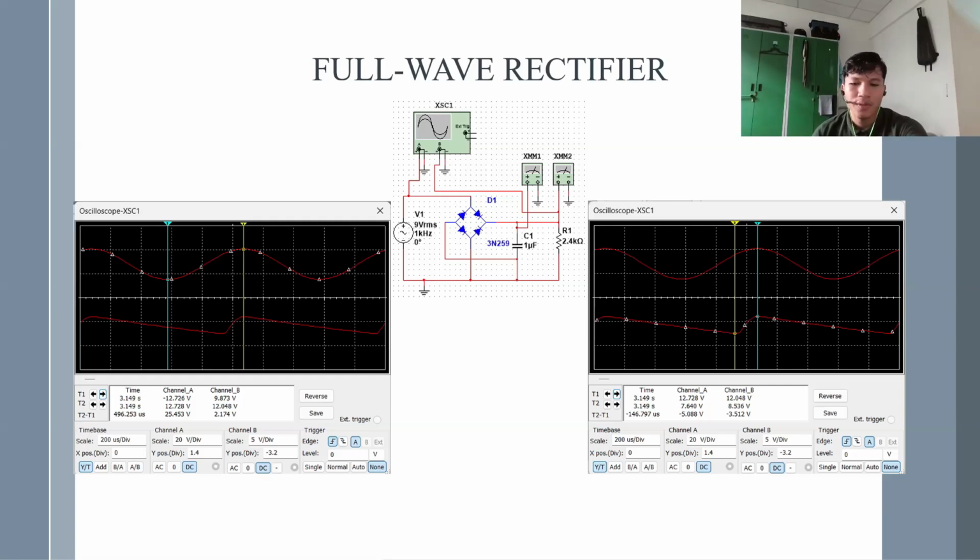8.536. So, the waveform at the DC voltage shows that the rectified output voltage is fairly stable and around 10 volts, consistent with multimeter readings. There is a small ripple present, which is typical in a rectified signal even with filtering capacitors. This ripple is significantly lower than the input AC signal amplitude.